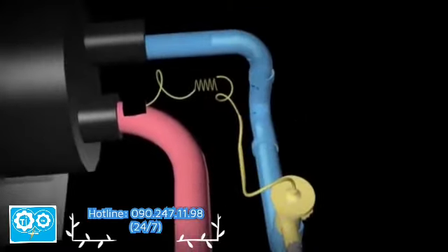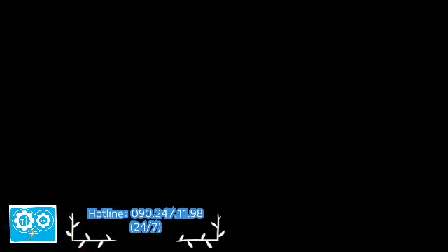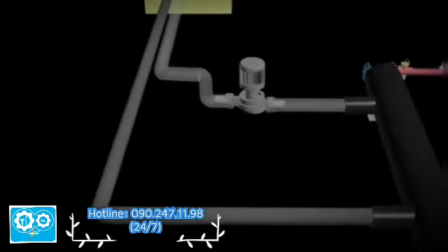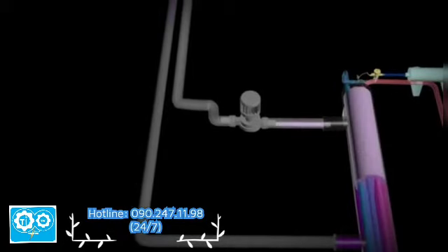Evaporator. The refrigerant in low pressure liquid form coming out from the expansion valve will flow into the evaporator at low temperature. In the evaporator, the heat from the chilled water which comes out from the air handling unit will be absorbed by the refrigerant due to the temperature difference produced.